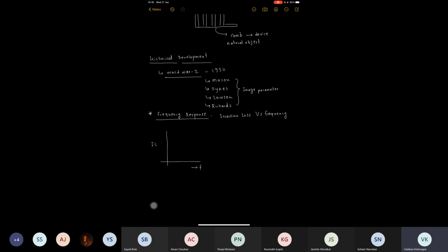And we see that from 0 up to a certain frequency fc, the signal will be propagated. So that means the signal in the low pass region, in the lower frequency band, is getting propagated, while the signal after the cutoff frequency is not propagating because the insertion loss is going to become too high for that particular filter when it crosses the frequency fc. So there you will find insertion loss will increase in the stop band. So this particular type of frequency response, we call a low pass filter response.